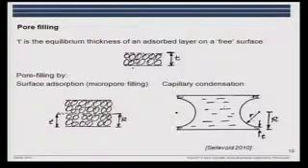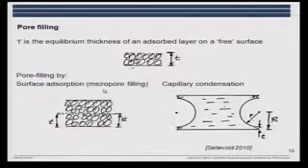So again, if we look at the surface, initially, starting from a dry material, we have a layer being built up on a free surface. And at a certain point, the small pores will be filled. That's here called micropore filling. And then later, we will have the capillary condensation. And here you can see this is actually the adsorbed layer, which is small in this drawing compared to the size of the pore where we have the capillary condensation.